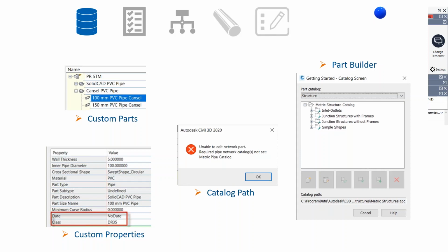The pipe that you created, yes, it's in the drawing, and your recipient or your colleague can label that pipe. They can make minor adjustments to it, but they cannot create their own 325 millimeter diameter pipe because they don't have it defined in their own catalog. So best practice indicates the very second you start adding or modifying your pipe catalog and you expect other people to use it, you need that catalog file available.